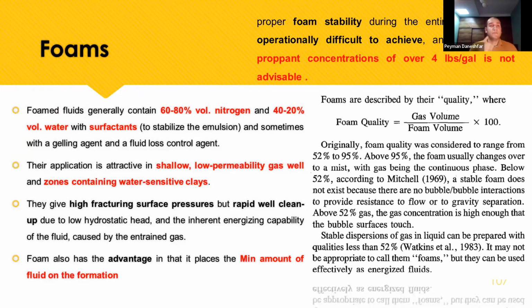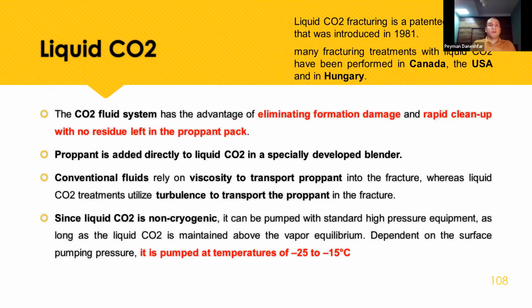So again, the important point is that we can use foam fracturing in shallow wells, in low permeability gas wells, and in zones containing water sensitive clays. Foam also has the advantage that it places the minimum amount of fluid in the formations. Another one is liquid CO2.